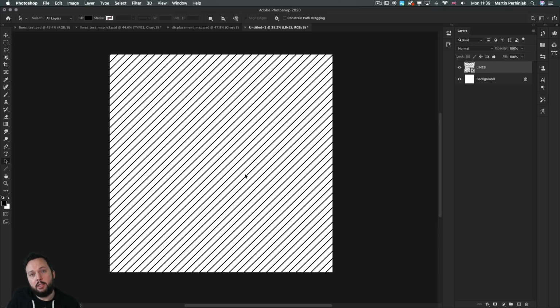Now, the reason why it's better to start with vertical lines is because that way your smart object document is set up aligned to your original document. It's always better to set up a smart object without any rotation. So keep it either horizontal or vertical, whatever you place inside it, and then do rotations and transformations already once it's saved as a smart object.